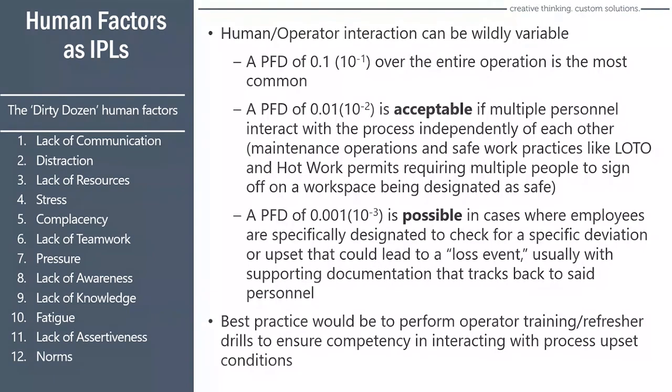And that number is obviously debatable. And you may say, well, my operators aren't typical, they're much better than that, and that may be true. But when we do a LOPA, we usually take into account a failure rate of about 1 in 10 for an operator. So let's go back to our initial example. And that initial example was filling that acetone tank 1,000 times a year. And if you have a failure rate of 1 in 10, that means that 100 out of those 1,000 opportunities, that person's going to overfill that tank without other safeguards. In other words, they're going to miss their ability to shut off the valve at the right time. And that is not atypical.